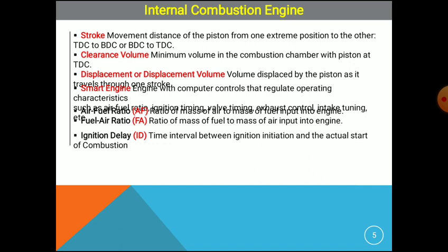Then there is the air fuel ratio, the ratio of mass of air to mass of fuel input to the engine. Fuel air ratio is the ratio of mass of fuel to mass of air input into the engine. Ignition delay is the time interval between the ignition initiation and the actual start of combustion.